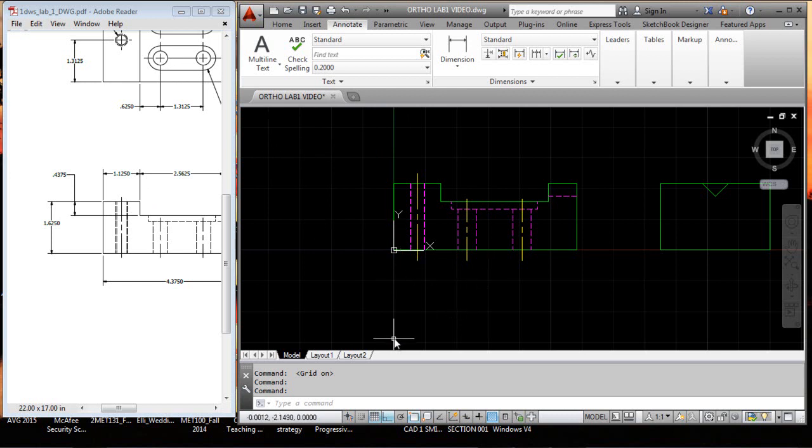Now we'll have to turn the snap on and off when we need to use it. You don't want it on when you're creating a dimension, because it won't necessarily snap to the end of the line. So I'm going to put this one out there, and if I turn the snap on now, I'll go out two sets of grid and go ahead and snap that.